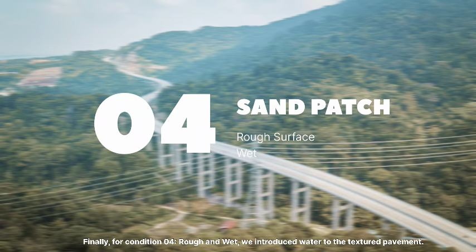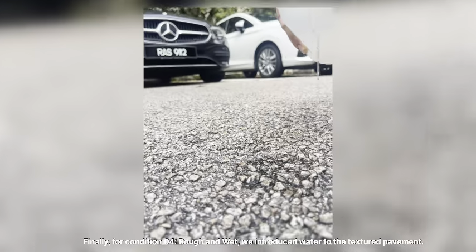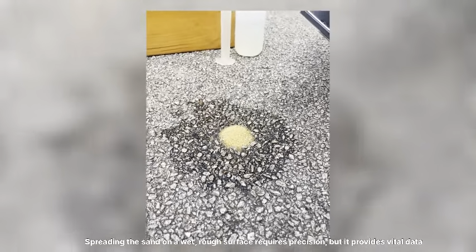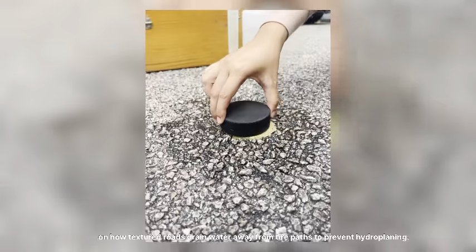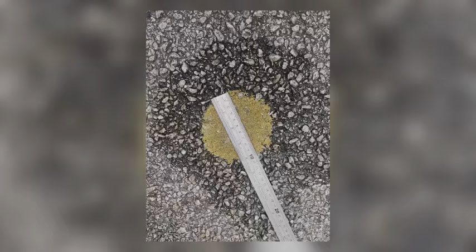Finally, for condition 4, rough and wet, we introduced water to the textured pavement. Spreading the sand on a wet, rough surface requires precision, but it provides vital data on how texture helps roads drain water away from the tire path to prevent hydroplaning.